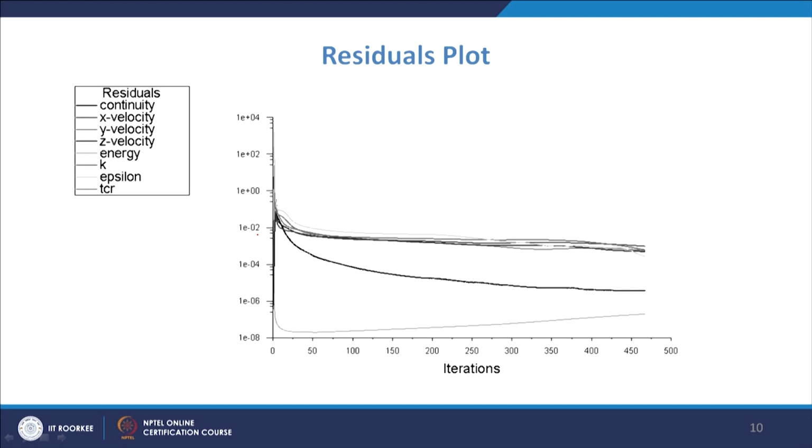So, that way on the monitor you can have the visual display, and then you ensure that the solution is complete. During that process, if the geometry is simple, it may take less time, but in most cases it will take a large amount of time. Maybe sometimes the convergence rate is very small, or it is showing abnormal behavior. So, we have to choose the relaxation parameters also.